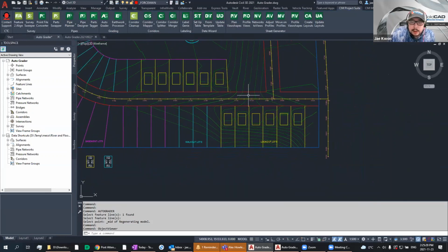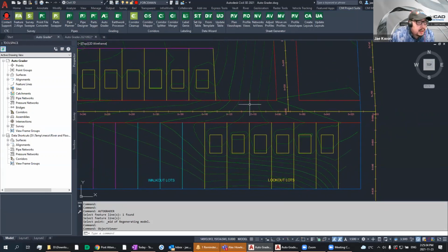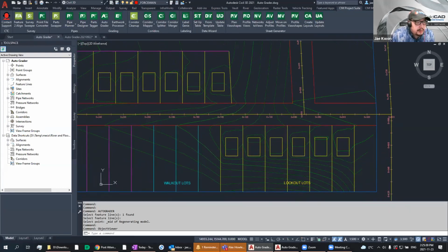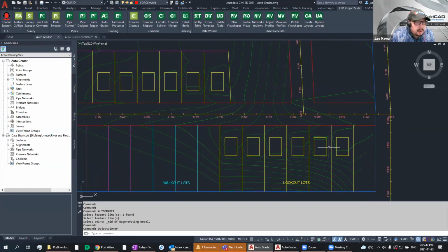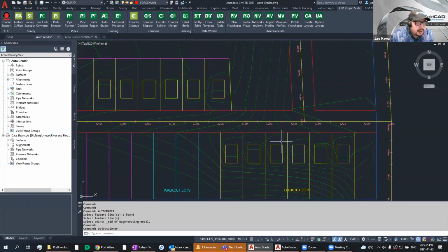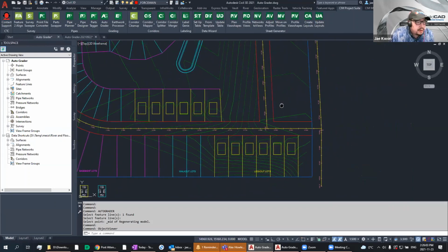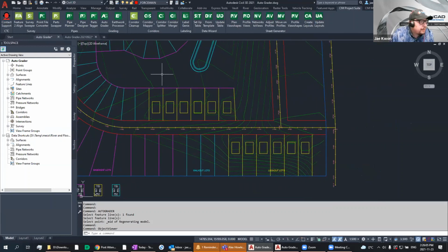Okay, so those are sort of like the standard usages. Just to recap, it's not just concentric grading like we do in out-of-the-box grading tools in Civil 3D. It can do perpendicular, whether it's new objects or existing objects, and it can grade by template. So right now I chose a very simple rectangle, but you can make it as complex as you want for the template. Now let's take a look at a couple of different use cases, a couple of interesting use cases that I've been looking at recently.